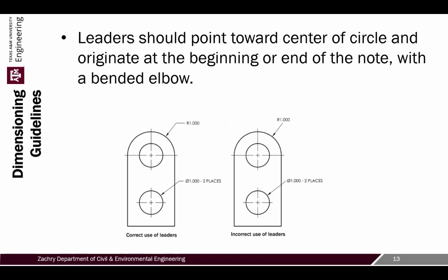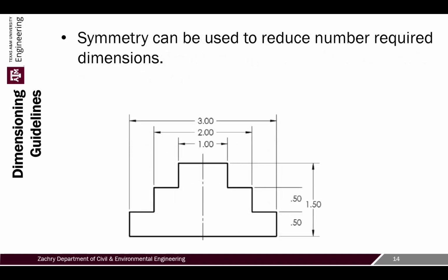And this is another place where, like what I was talking about, I gave a diameter here of 1 inch. Well, this one's also 1 inch, but I used a note in 2 places to say that that's what this dimension is. So I'm not having to look for the size of this hole because this one says, hey, you got two holes here and they're the diameter 1. So there's a good example of that.